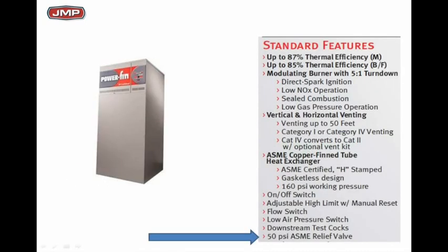Well, it would be okay unless you used a boiler, like in this case, with a 50-pound ASME relief valve. So now what's going to happen? Your boiler's going to pop. As you start heating it up, the relief valve is going to pop. So it would not be big enough, because the equipment we're trying to protect limits us to a 50-pound ASME relief valve. Now, not all boilers are that way.